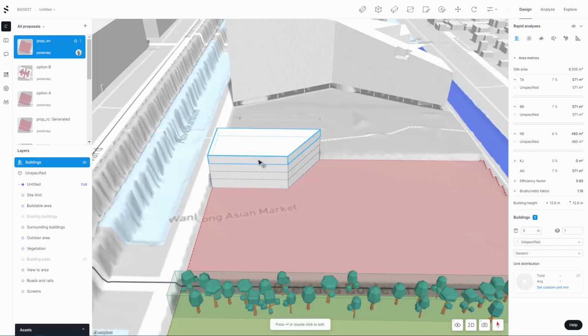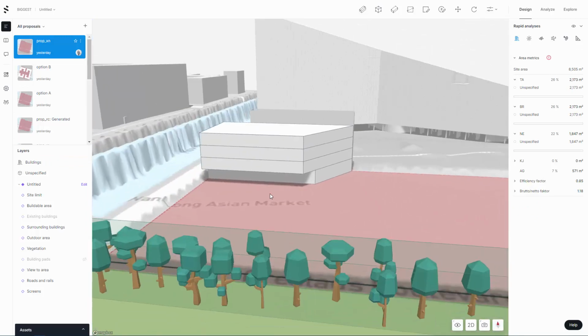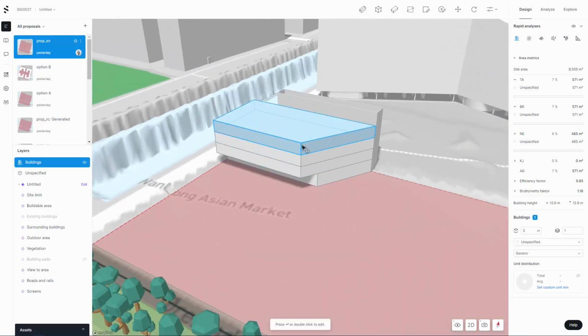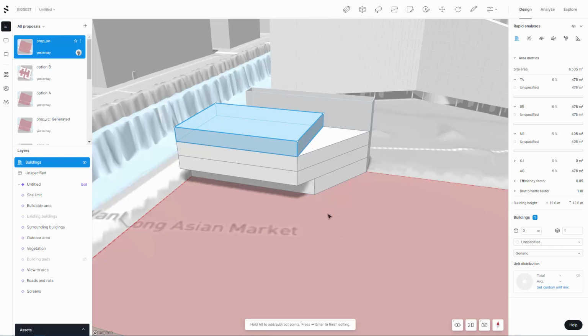So here you'll see you can select on each individual floor plate, and let's say at the bottom level this is going to be recessed in a little bit. I can go and click on that little node there and then take that in a little bit. So I'll take that in, say, 4 meters, -4 meters. And we can start to shape up our building like that. So there's these great little tools which allow you to manipulate the design as needed, and you can have a bit of fun here. So again, 45, and we're starting to get some shapes happening with our building.